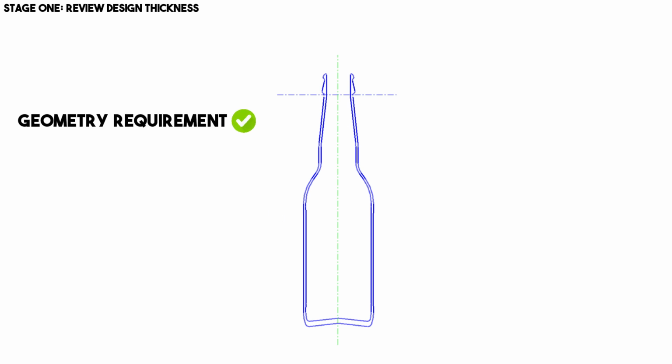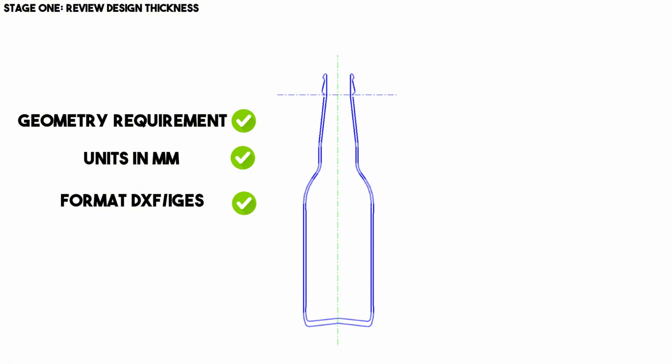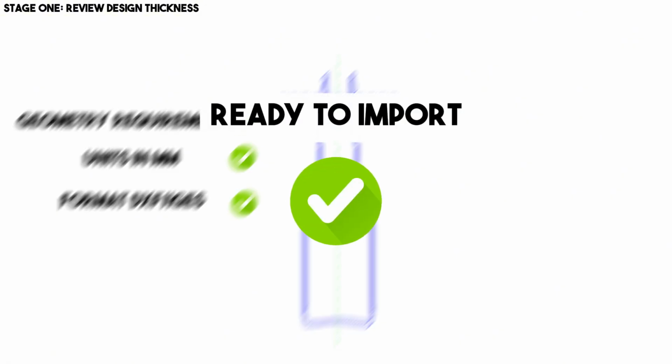Follow the geometry requirements outlined just now and make sure the units are in millimeters. Now export them into IGS or DXF format. They are now ready to be imported into Elfen gd3D.